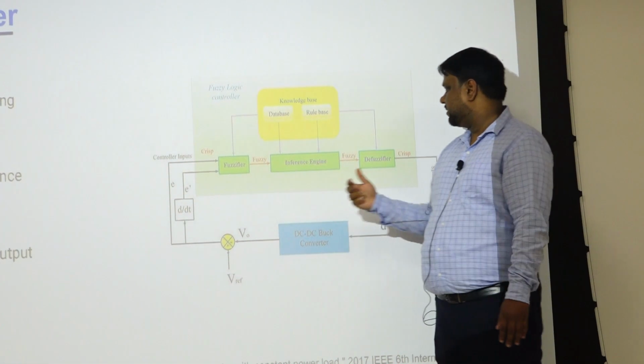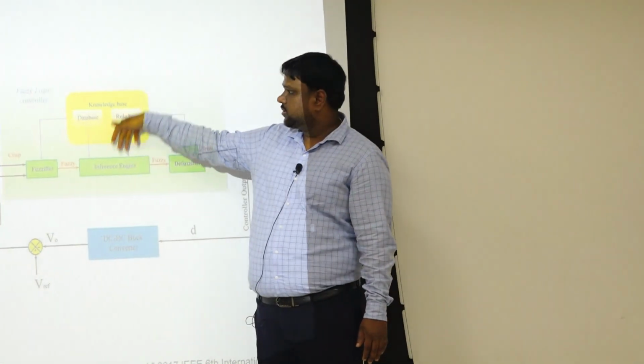You have a fuzzifier and defuzzifier, and you add your knowledge, what you say if-else conditions. If input is this, output is that. So, that inference engine you have to feed the information, like what are the conditions you want to feed it. Then the input parameter it will fuzzify, it will pass through this information, true false, then it will defuzzify and generate the duty cycle. The control details you can find in this paper.